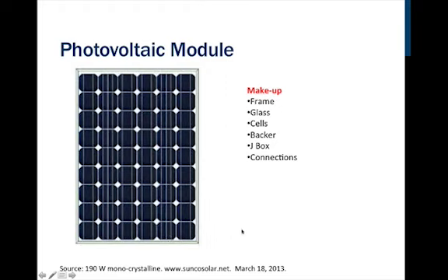And that glass, there's different standards, but in general, that glass can withstand a 1.25 inch hailstone moving at 90 miles an hour. And on the back side of that module, these white pieces that you see here, here, here, that's the back sheet. So we have a protective layer on the back side, which is a Kevlar, a tough plastic, but it's vulnerable though on the back side. Plus there's a junction box with wire connections on the back as well.